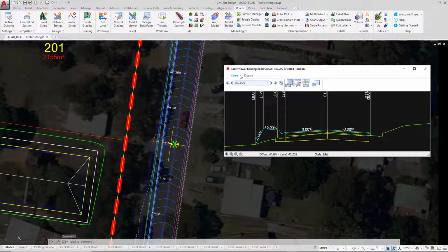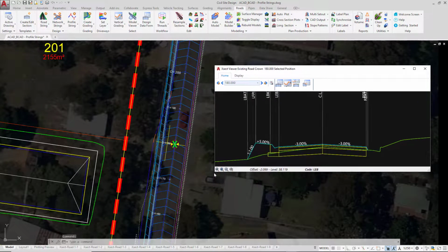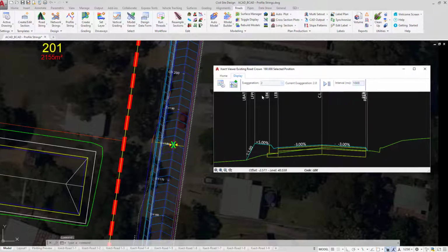Make sure that, as with all the lessons within this particular course, you always have your cross-section open at a nice scale, and it's not all scrunched up into the corner. You can open that up and see what's happening. Have a look at your display exaggeration and make sure it's set to a reasonable value in there as well.